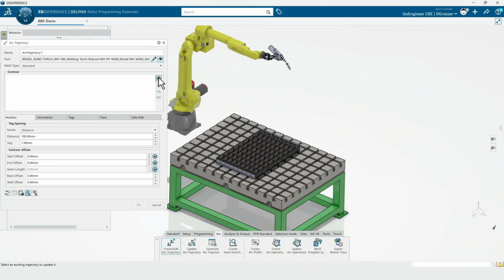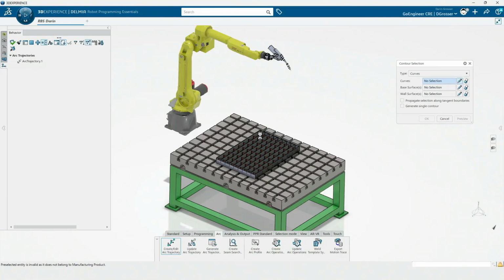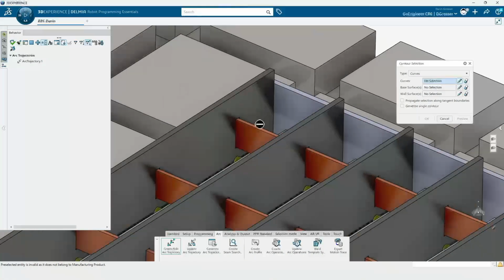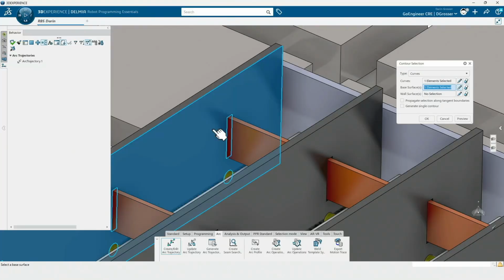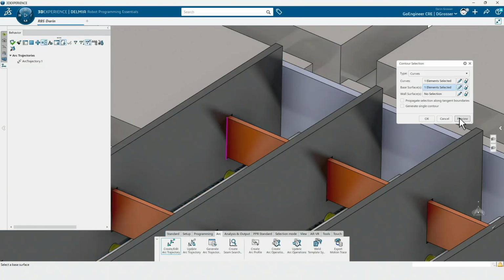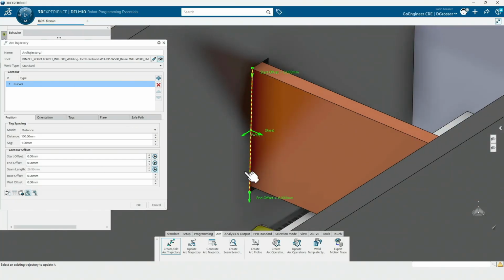So what I like to do on a project like this is start to define contours. Now, the contours themselves could literally be edges of the part, but in a lot of cases, there's gapping built in, chamfers built in, and you end up with kind of virtual edges that you need. So when you pick an edge to define it, you also define it based on other faces, and that allows us to hit a virtual intersection versus a literal edge.